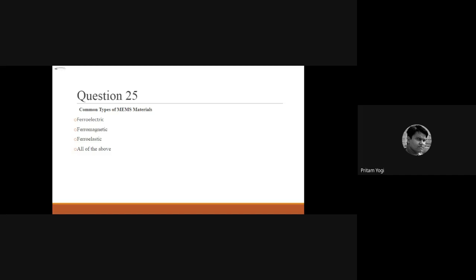We already discussed that the litho is the same thing. Suppose we want that IDE pattern, we can take a mask and pattern it using litho, and then deposit the metal by a PVD technique, like sputtering or any technique.